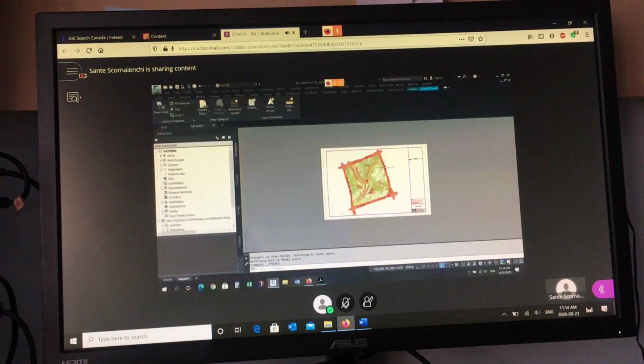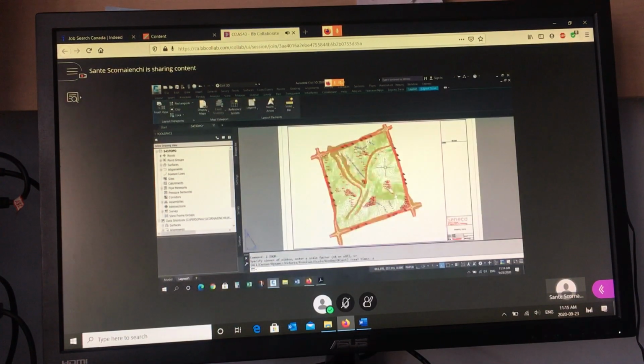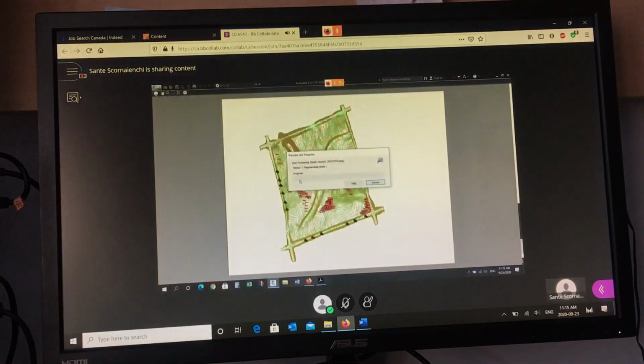So that's how you create the viewport. That's how you get your scale. So for this particular drawing, you're going to use a zoom factor of 0.5 to establish a 2000. So you're going to print this at 1000, but everything in that viewport is half the size. The scale will actually represent 2000. Okay? So now if we go to plot, and do a preview, you're all ready to go.